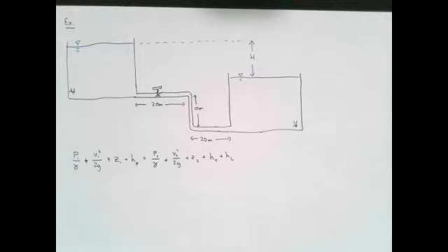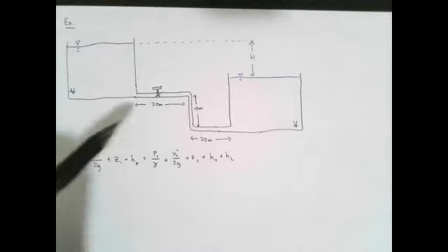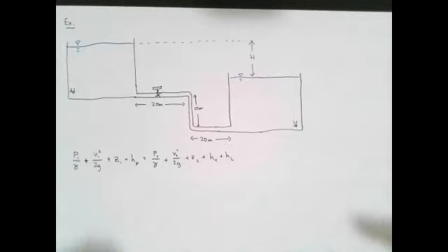flow. For example, next week we're going to learn about Manning's equation, but that's specific to uniform open channel flow, right? We're going to learn about the Hazen-Williams equation, which is specific to pressurized pipe flow. So the energy equation, some people call it the universal equation, and that is because this can apply to any system where we're studying the energy. So we write down the energy equation. We want to use the energy equation.